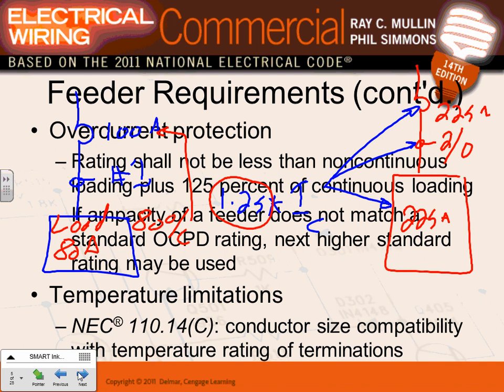When I say there's a 225 amp panel, the one that you guys sized for me, can I pull 225 amps out of the panel continuously? No. How much can you pull out of it? Only 80% of the rating of the overcurrent protection device. That's by code. So the question would be, did I undersize my panel? No. Why? Because when we came up with the 225 amp panel size, we already added the factor of 25% extra. Do you see how important the 25% factor is? Because when your system is up and running, you can only take 80% out of it.